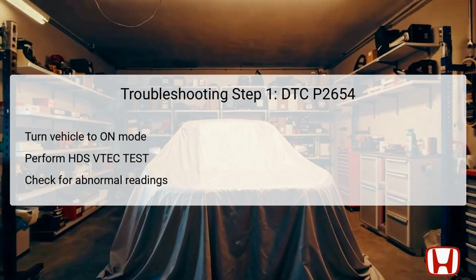For the initial troubleshooting step, begin by turning the vehicle's ignition to the on position without starting the engine. Ensure that all diagnostic equipment, particularly the Honda Diagnostic System, HDS, is ready for use. Once prepared, perform the VTEC test using the HDS tool.